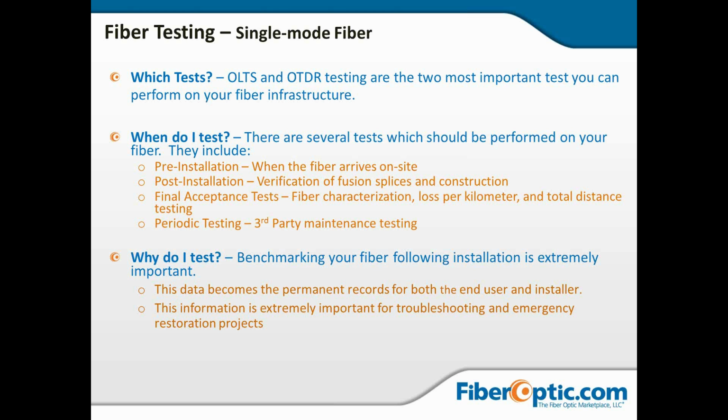In Barbados, I found a couple of problems developing where people were messing with the cable. We shared a manhole in several locations with the power company, and the power guys were messing with the cable at a splice location and causing some macro bends, which we found by doing periodic additional testing.